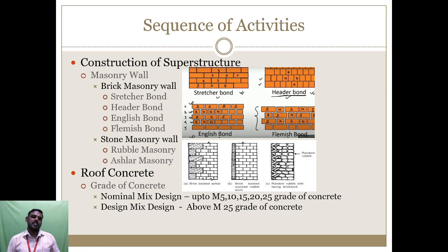Okay, in the brick masonry side view we are seeing it's in a stretcher arrangement, which will come under stretcher bond. In header bond, only the header side is possible to see in the side view of the brick masonry. Then English bond, which is regularly used by the masons. In practice also, they are following this successful method.